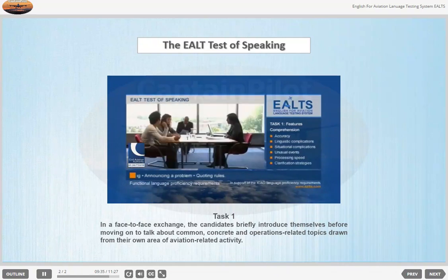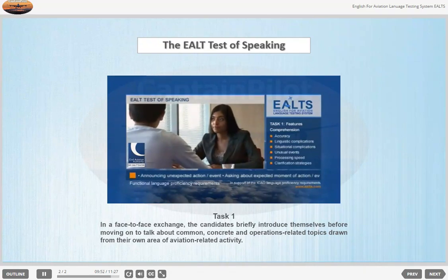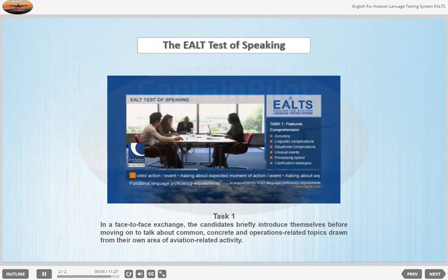When clearance to descend below the transition altitude is given, ATC advises pilots of the track distance to touchdown. We try to make descent continuous with no level flight necessary. Approach control gives more information on the distance from touchdown between this descent clearance and the instruction to turn onto the intercept heading for the ILS localizer.